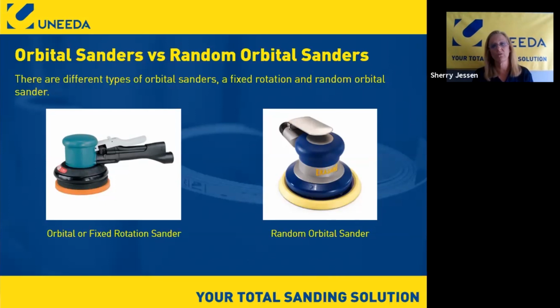First of all, let's talk about two different types of sanders. You've got an orbital sander, or a fixed rotation sander. This sander has no random pattern to it. It is generally a little bit more aggressive. I've used these a couple of times in automotive. I don't see many of them in woodworking. I have used one or two in solid surface to blend seams.